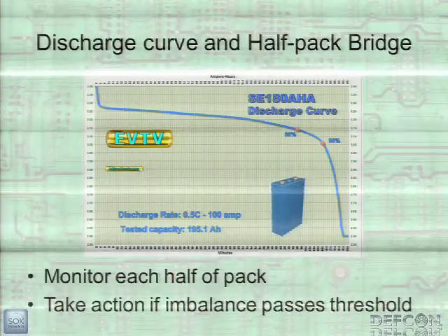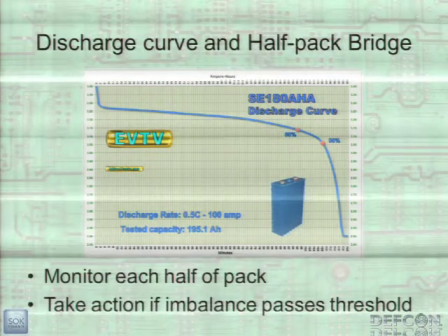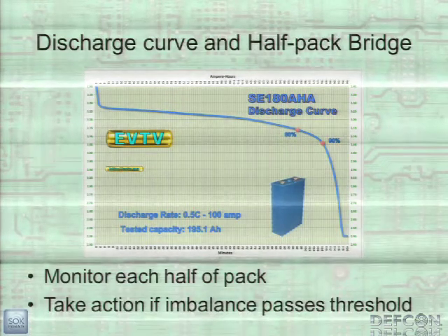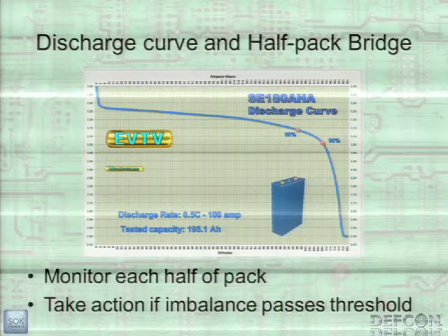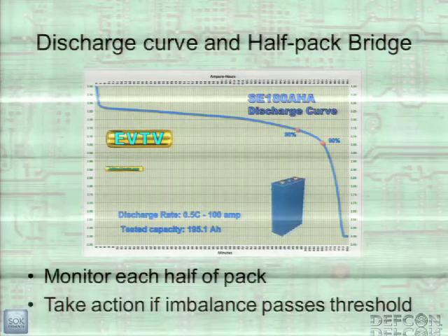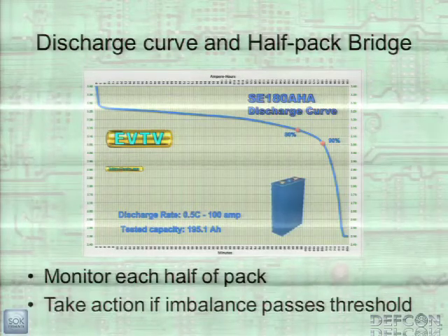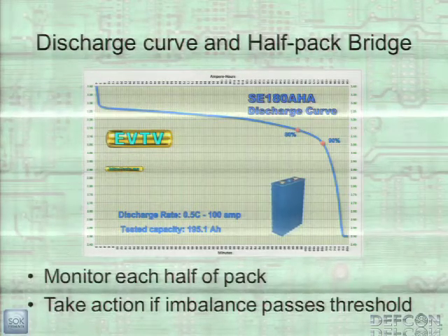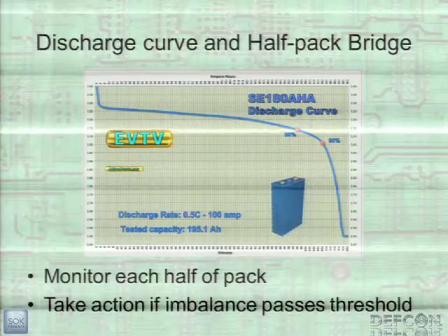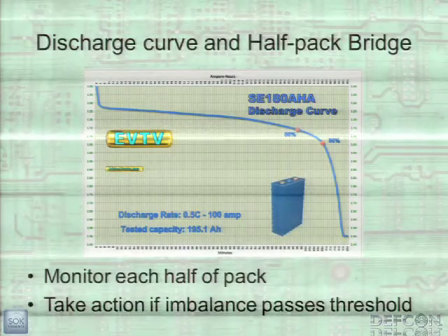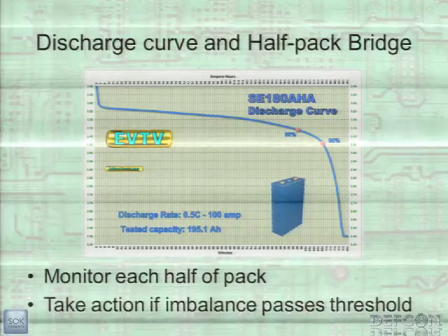So this shows the discharge curve. You can see it's really flat. Your voltage is at about 3.2 volts for almost the entire time, but at the very end of your charge cycle, it'll shoot up quickly. If you get much over 4 volts, your cell is destroyed. Also, once it gets down to 3 volts, it's just about empty. If you take it down to 0 volts or below, it's destroyed. So you have to keep it there in the middle.